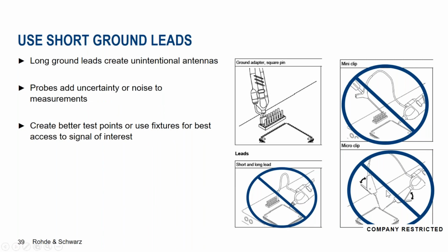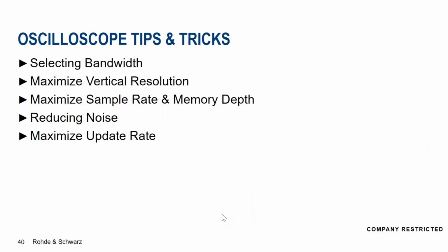One other quick tip here is, as we show our active probe, even on an active probe, you can degrade that performance pretty quickly by using all the fancy adapters that are in the accessory kit. So this isn't just for passive probes, it's something we consider for all probes.